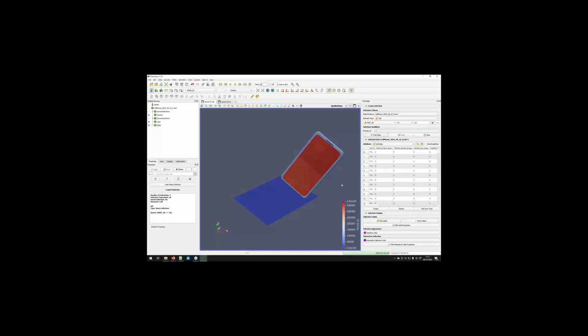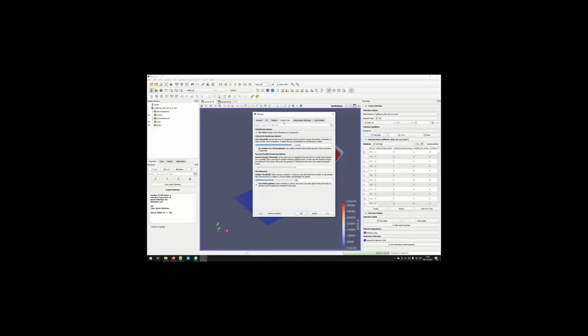And we have the end of the questions. It's another question from me. Also, is there a scope for reducing rendering quality to maximize performance? Yes, there are lots of settings in ParaView. So you can look at the settings here. In the render view, you can play with lots of thresholds, lots of LOD, so decimation on the fly.